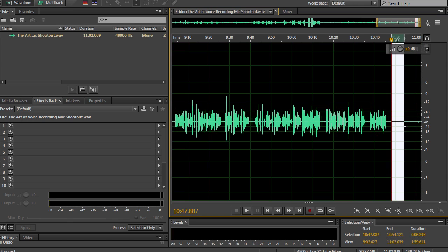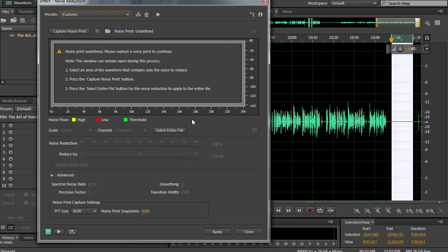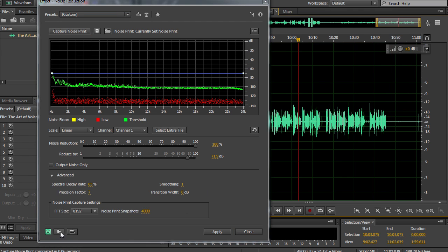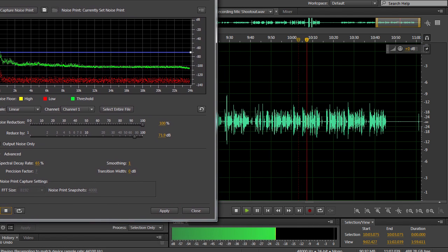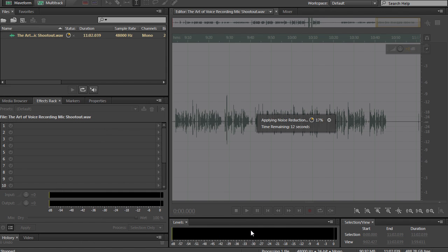First, it can help you to better tackle noise reduction in post-production. The type of noise reduction I am referring to here is broadband noise, which is different than a dog barking outside. Noise reduction is not something that you will want to use a whole lot because it can cause some nasty sounding artifacts, but sometimes it's unavoidable. Depending on the conditions of the recording or the location, you may have recorded some noise that needs to be dealt with. Recording 10 seconds of silence at the end of your session will give you an additional tool to be able to tackle this.